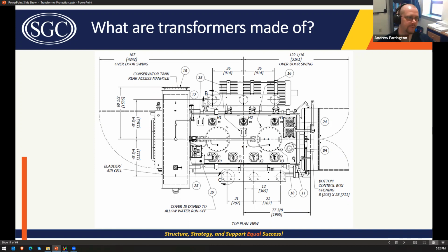Same thing with breakers. I'm not sure if they mentioned that too. If you take your breaker and you rotate it such that you have 1, 3, 5 on top, and then 2, 4, 6 left to right on bottom. And this is something that does get missed in designs, because a drafter will take a transformer and, because it's more convenient to mirror it than to rotate it around, especially with breakers, you'll see it a lot. And that can really screw you up. I've seen it happen more than once. So you can't mirror, you have to rotate.